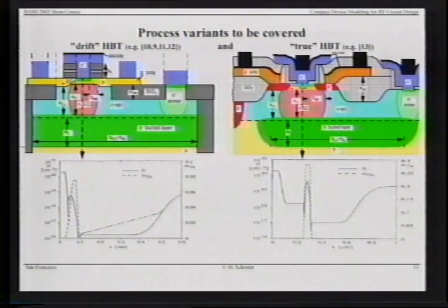But there's one more type of technology, which I only know one company that fabricates it, actually in production. That is similar to GaAs HBTs, what we call a real HBT. And you can see here, if you draw a line underneath the emitter, the profile has a moderately doped emitter, a highly doped base, and a box germanium profile.